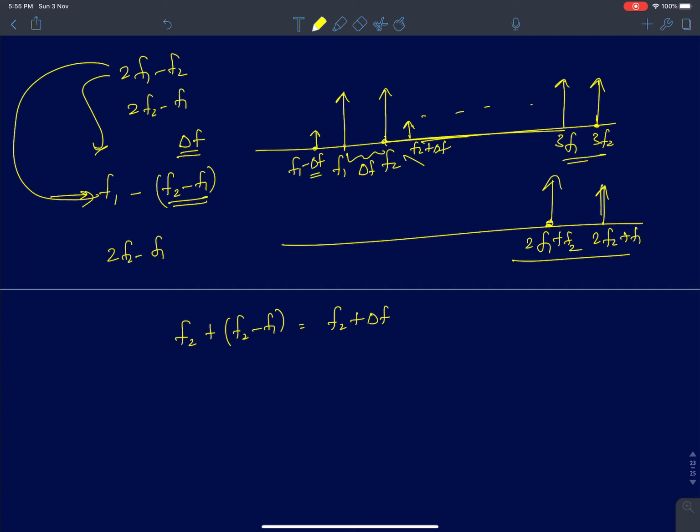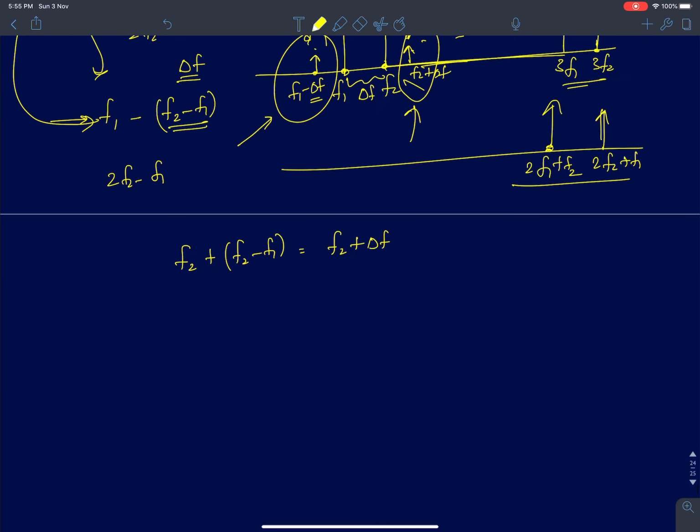Now if your delta F is very small, you can see that these two terms occur very close to the interferers themselves. Now if your signal is either here or here, then that's a problem for us. We are not only going to receive our signal but also components from the two interferers. So this product is called intermodulation. These are IM products, the intermodulation signal.